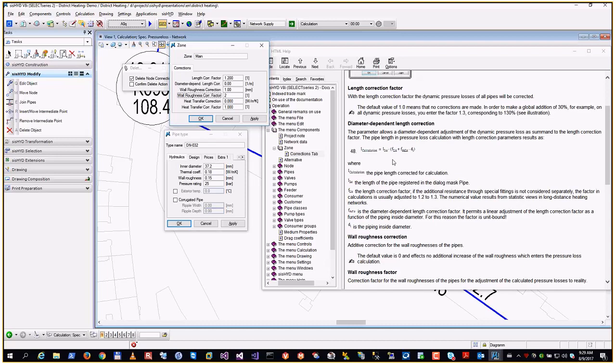So if you have a factor, you would account for larger pipes. Larger pipes would get a higher correction than smaller pipes. Those are just factors to get the model results in sync with the reality results, which means you have to have data and measure pressures and flows, if possible, at the constant state of the network.